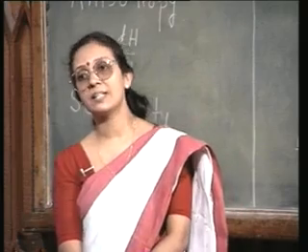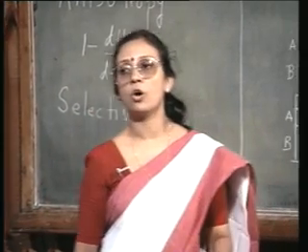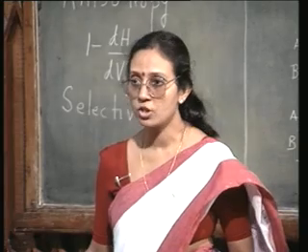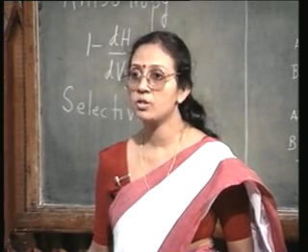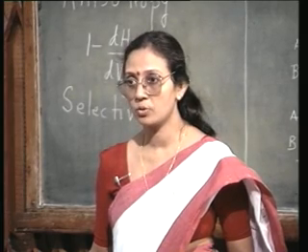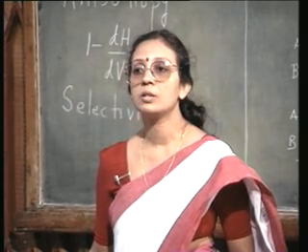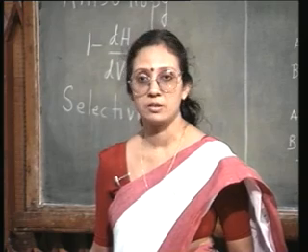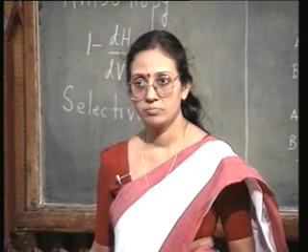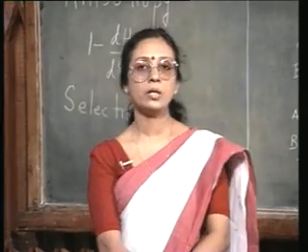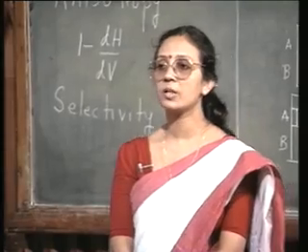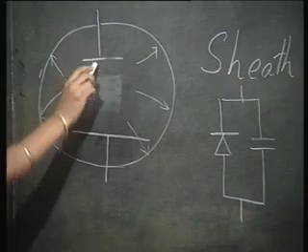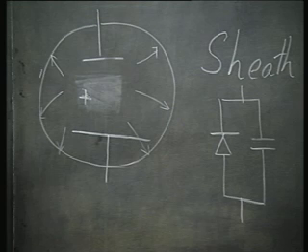So, in practice, you can alter the sheath potential, therefore you can alter the electric field towards that particular electrode, and you can alter the ion bombardment energy. That is to say, if I have one electrode smaller and the other electrode larger, then the voltage developed across that smaller electrode will be much larger, so that the electric field here will be much larger.